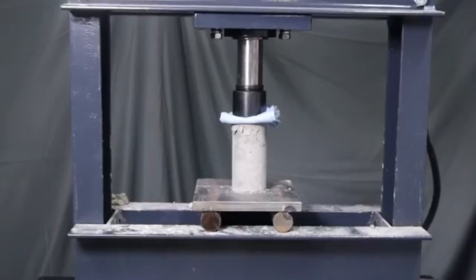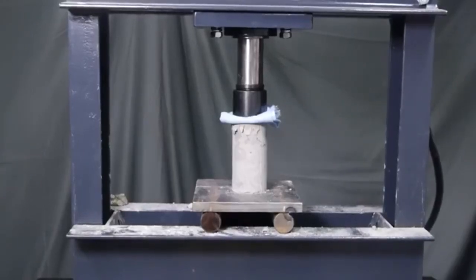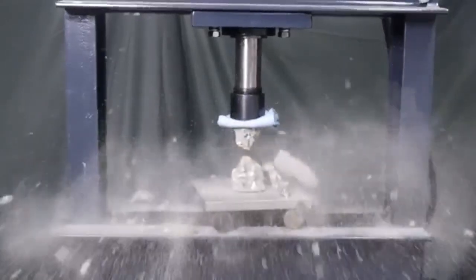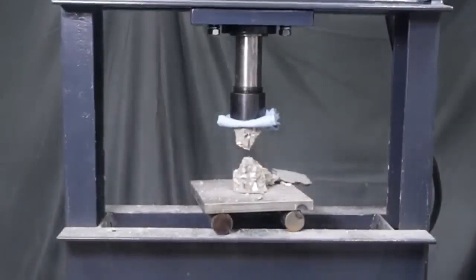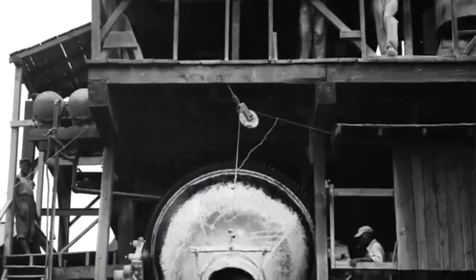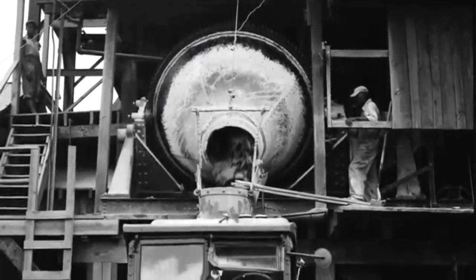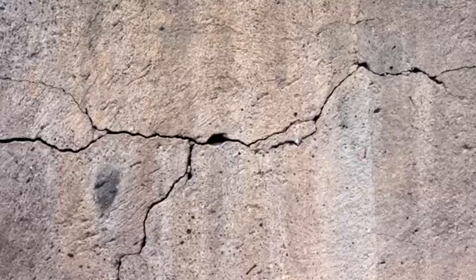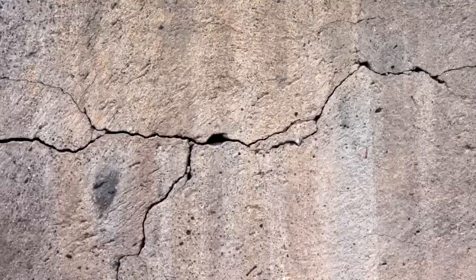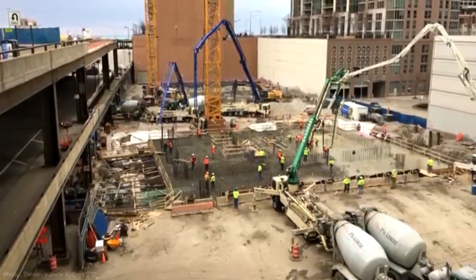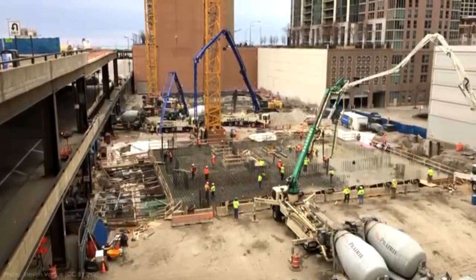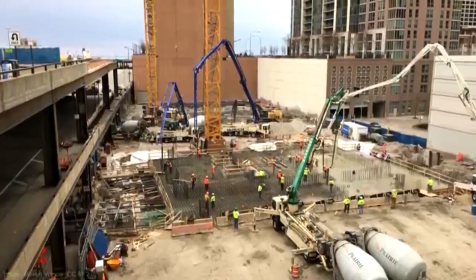Despite its excellent qualities as a structural material, concrete has some weaknesses too. One that we've discussed in previous videos is that it has almost no strength against tension. Concrete can withstand a tremendous amount of compressive stress, but when you try to pull it apart, it gives up easily. Concrete's other weakness is that it's brittle. It doesn't have any give or stretch or ductility. Combine these two weaknesses and you get cracks. Concrete loves to crack. And if you're designing or building something made of concrete, understanding how much and where it's going to crack can be the difference between the success and failure of your structure.